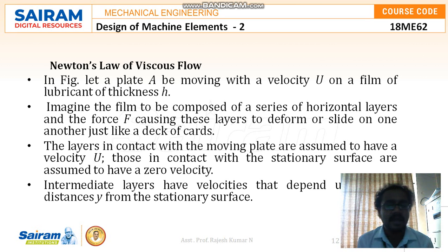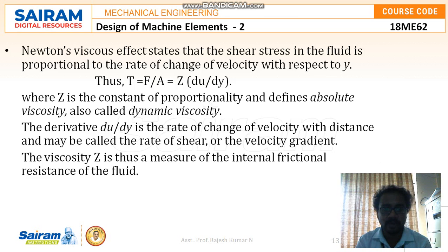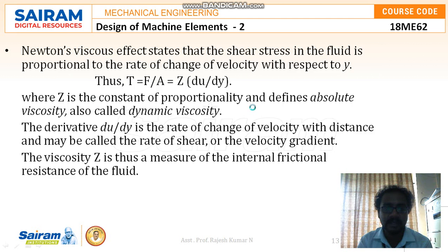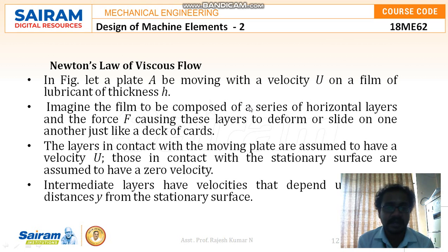First we will have a look at Newton's law of viscous flow, because it is very important when we are trying to understand lubrication and viscosity. I am talking about this particular sketch. First let me explain the content, then we will move to the sketch. In the sketch, I have considered a plate A moving with a velocity u on a film of lubricant of thickness h.